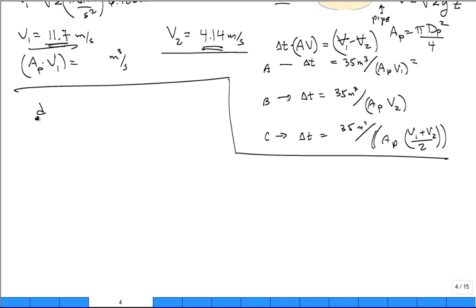The rate of change with respect to time of the mass of water in the control volume, with the control volume being the tank, is equal to a negative, because it's flowing out, the rate at which it flows out or exits. There's a mass balance equation. How do I write the mass of the water in the tank?